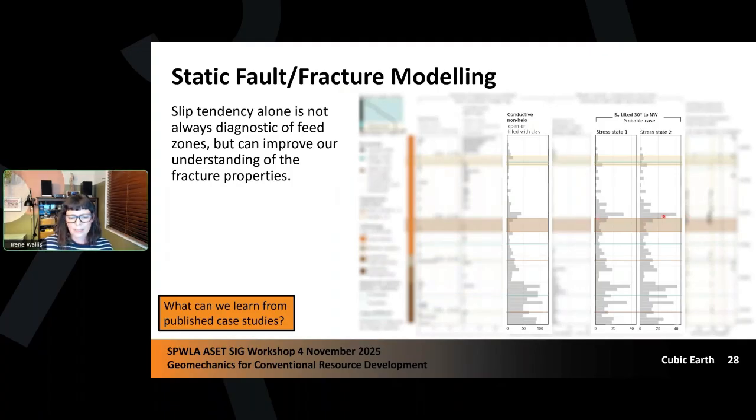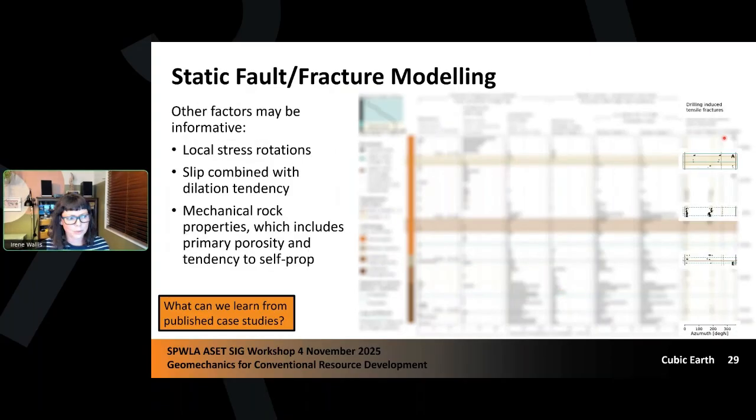What we're often finding is that where you get these localized peaks in fracture frequency shaped like this, there tends to be larger fault zones, and often large permeability tends to be around larger fault zones. This bottom unit here is actually an andesite, and what we're seeing is thermal parting, likely on flow banding, as well as jointing in the andesite that's not related to connected fractures.